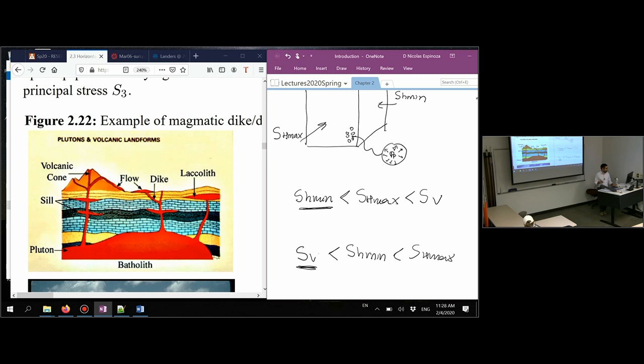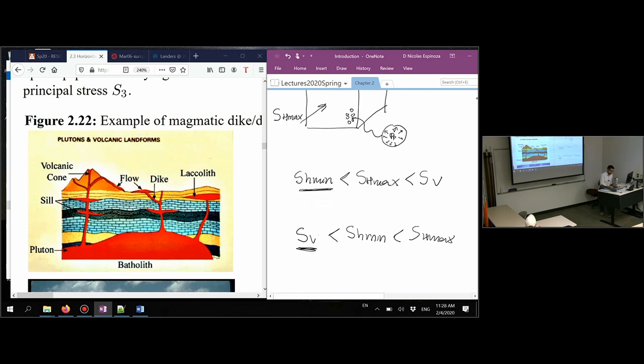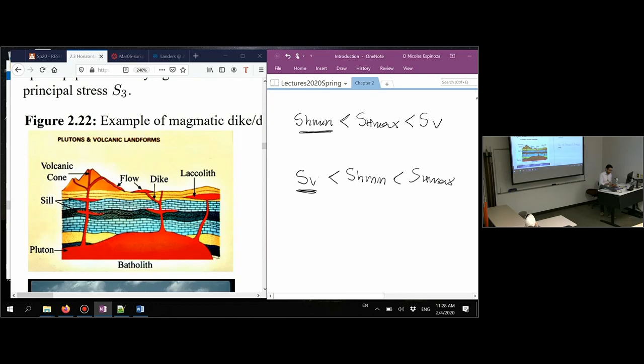For example, if you were to do a hydraulic fracture, and now it's not a magmatic dike anymore but actually a hydraulic fracture, and your fracture propagates vertically like this and then gets to a formation and starts propagating horizontally, this is what is called a T fracture. And that's going to be caused by the variations of horizontal stress with depth.